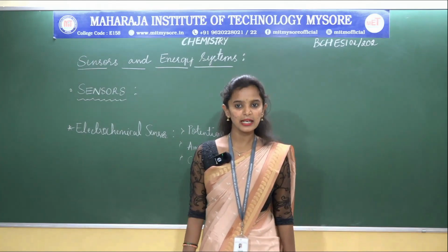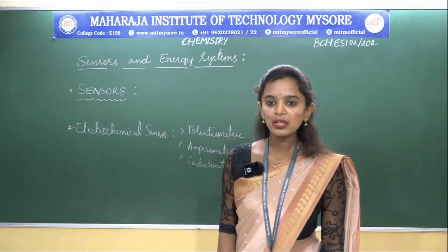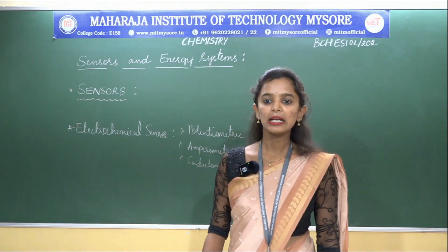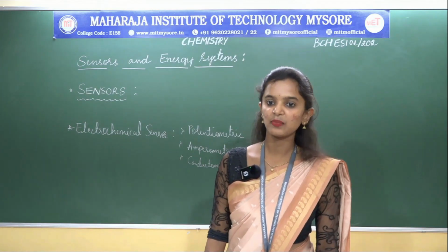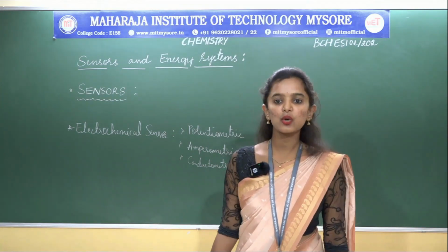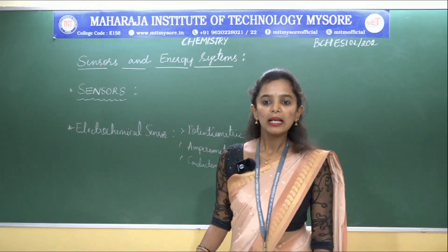Electrochemical sensor consists of a transducer element covered by a recognition element. The recognition element interacts with the target analyte and a signal is generated. Electrochemical transducer transfers the chemical changes into electrical signals. The electrical signal is related to the concentration of analyte.